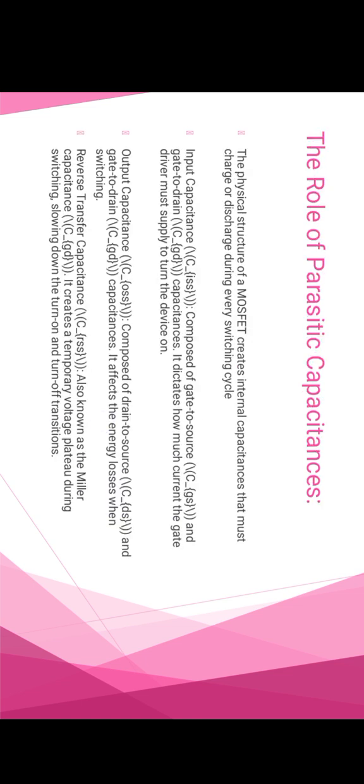The role of parasitic capacitance: the physical structure of a MOSFET creates internal capacitance that must charge or discharge during every switching cycle. Next is input capacitance. It is composed of gate to source and gate to drain capacitance. It dictates how much current the gate driver must supply to turn the device on.